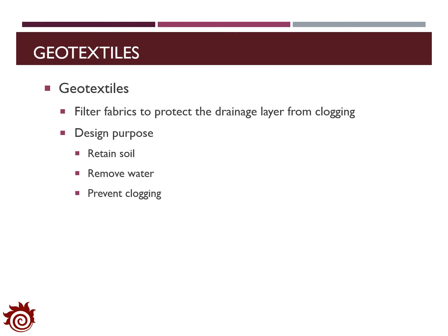First, the geotextile is usually made from some strong, tough, and rot-proof polymeric fiber, and it could be woven or non-woven fabric. Usually in the drainage system, the geotextile is applied to retain soil and remove water freely from the pavement structure. It should also have sufficient opening areas to prevent the potential clogging of the drainage layer.